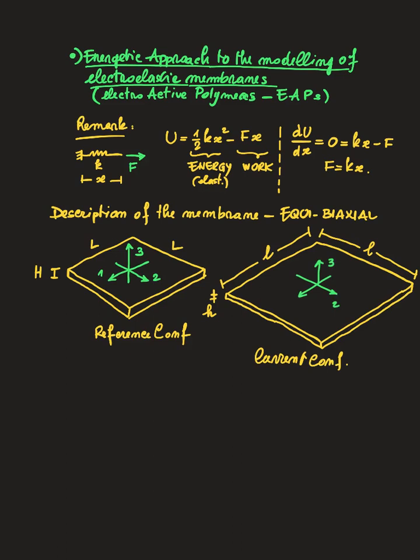First of all, I want to deduce the gradient of deformation. In this case, I just want to study a homogeneous deformation. I want to describe the deformation F that brings this guy into this guy, and I will already start in terms of the gradient of deformation, capital F.